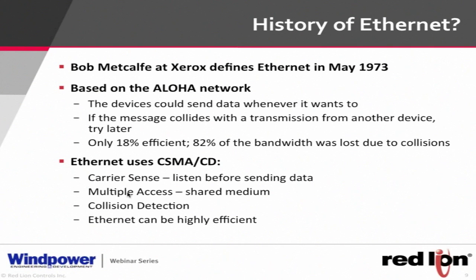And today or in the past, you've used serial type communication, which works fantastic, but it has limitations too. With serial communication, you have to daisy chain it if you want to extend it out. Then we have distance limitations and bandwidth limitations. So going to Ethernet is a very good idea because now we're able to get away from all the limitations that serial has. And plus, when you're using serial, you're kind of tied to a vendor.